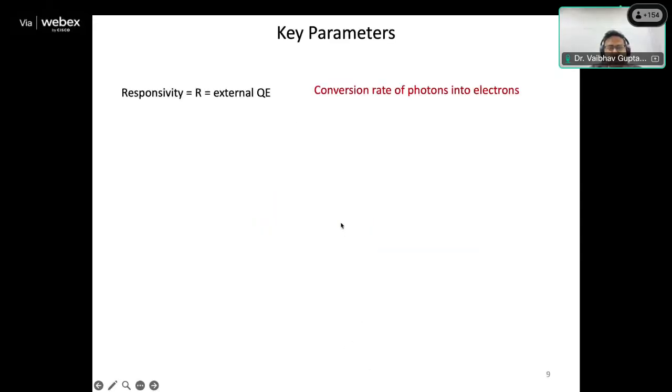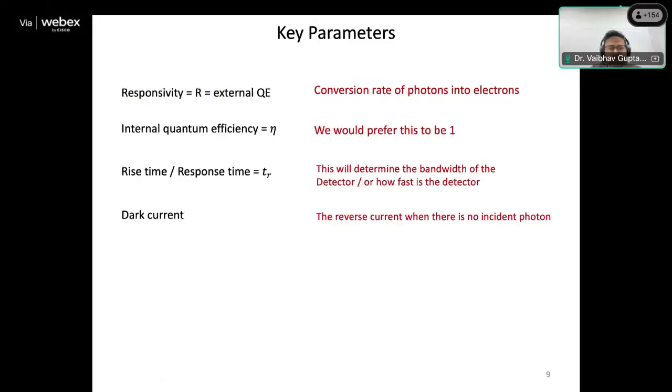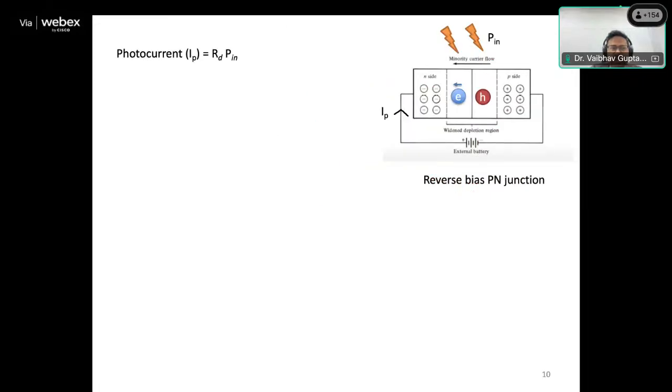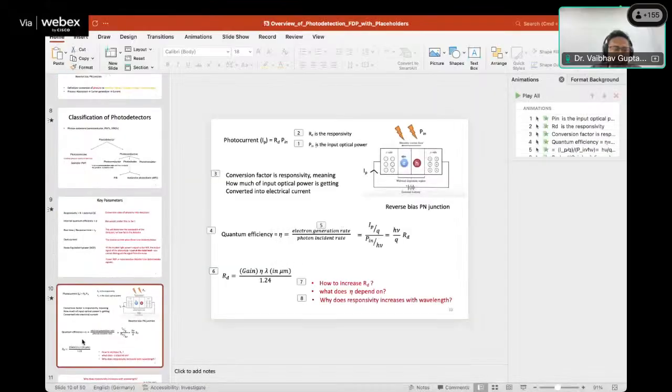And then we finally classified some important parameters. If you are a design engineer, which parameters should you take care about if you are going to build a photodetector? Such as the bandwidth, the response time, quantum efficiency, responsivity, NEP, all those things we established. And then I gave you some examples of how the formulas for each of these look.